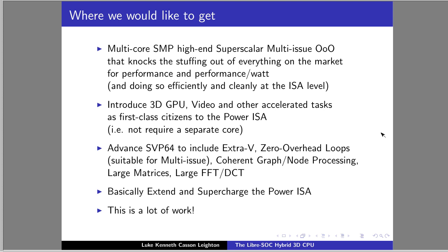So FP5 and FP6, when they are set into this special mode, actually use an implicit hidden load with increment. Load and increment pointer is the sort of thing that you used to see in the Motorola 68000 and the minicomputer instruction sets, the historic PDP-11. They've typically been dropped now from RISC cores because they're actually really complex, but they were a really necessary part of the process at the time. And as usual, things come back full circle.